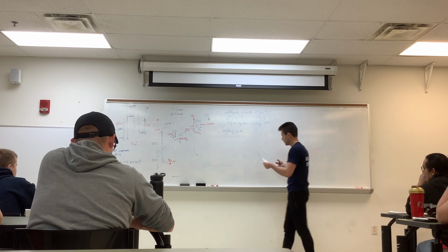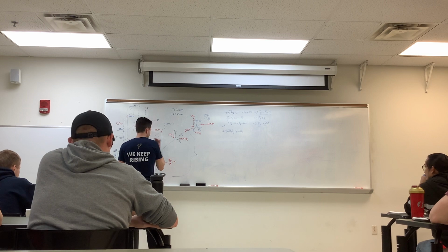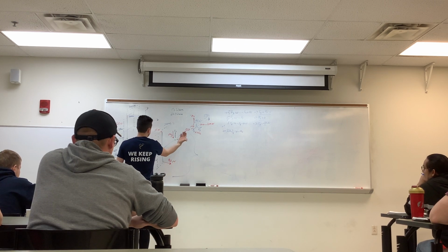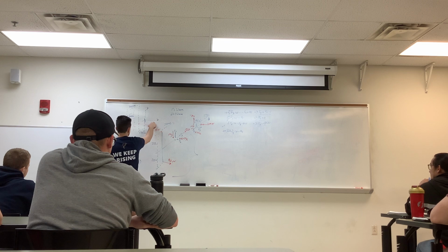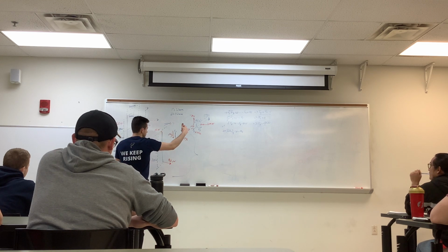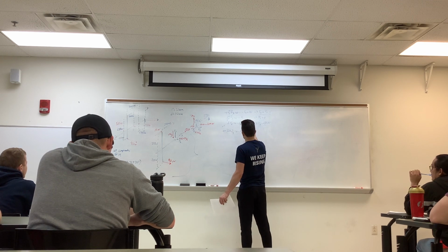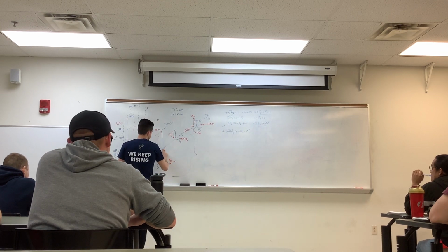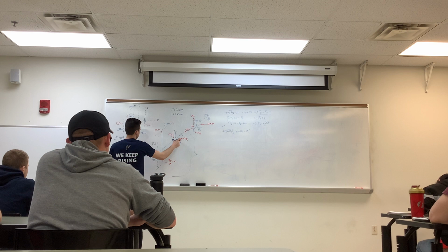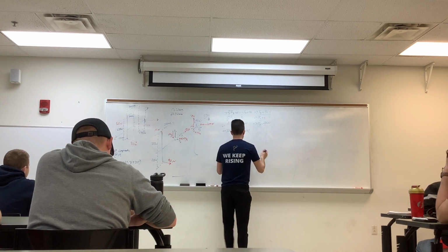I'm assuming positive here, negative moment, curling our fingers. This is opposing what we had as our positive axis for the initial problem. So, this will be minus 55 newtons times the moment arm, or the distance between the axis and our force, which is this 225 millimeters.